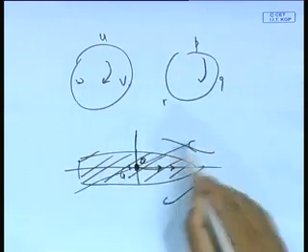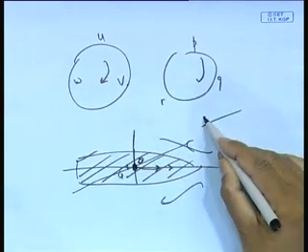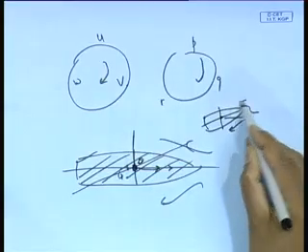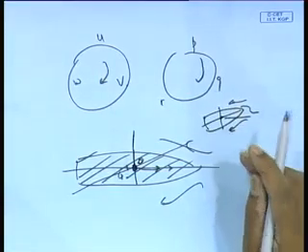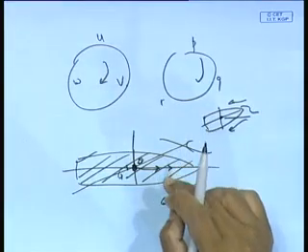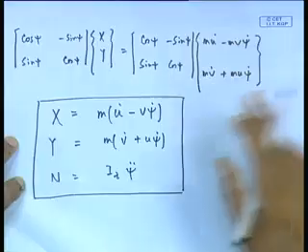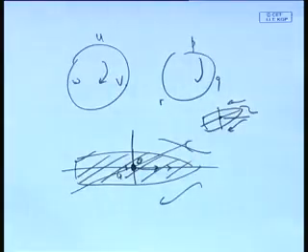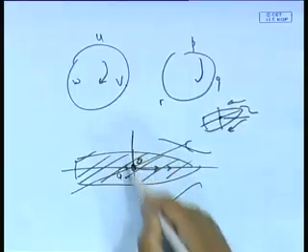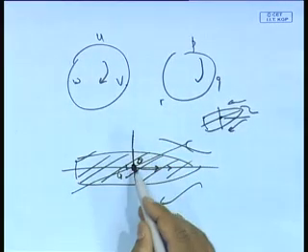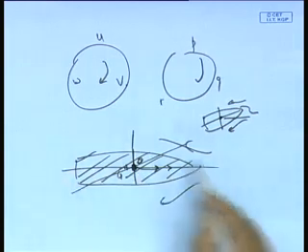See, for example, I rotate it about this line, I have this ship, and then I want to find out the flow past it. Okay. So as a result, quite often it is very common to apply these equations with the origin taken at a point which is not the center of gravity. However, it will not be along this line, because remember, the ship is symmetric, port starboard. So normally you will take an O which is along the center line.